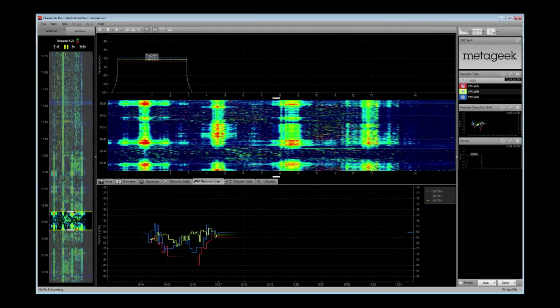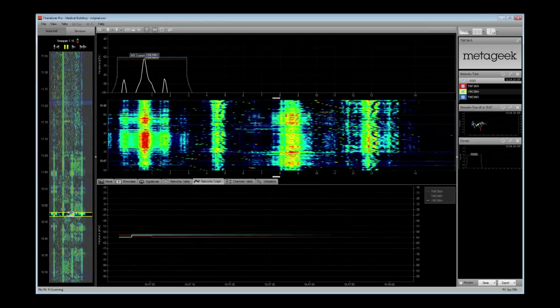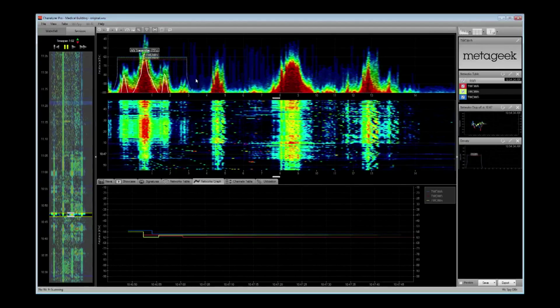And then you can create a snapshot of that transmitter, turn on the color by utilization so they can see how prevalent that is. And you can say, okay, there is an AV transmitter in the environment that is causing a lot of activity on those particular channels. So we'll add that as a density view so they can see how much noise.